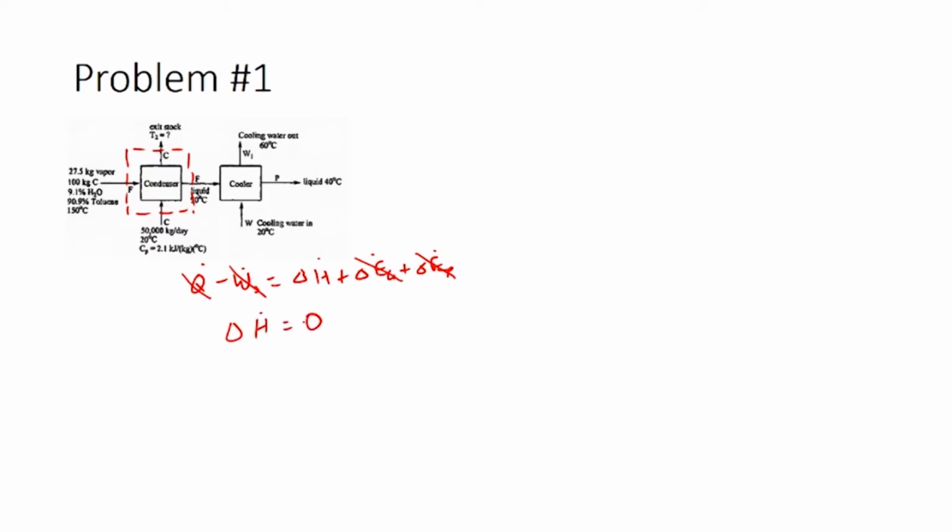Now that you have delta H dot equals 0, we can write the expansion for H dot and identify the value for the temperature. Here you have only constants given as Cp values, which means you would not have a very complex polynomial, which we usually end up with when we calculate temperature. Usually we would have a third order or a fourth order polynomial which would be difficult to solve. Here it would be a simple linear equation which can be solved. So, let us try to do that.